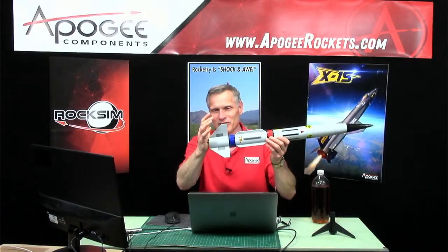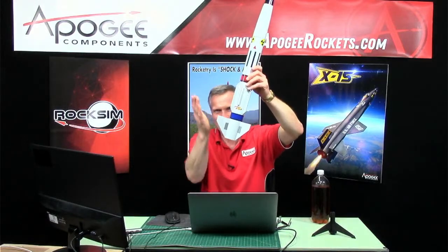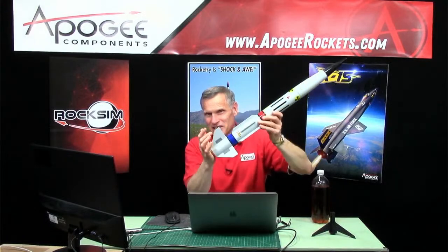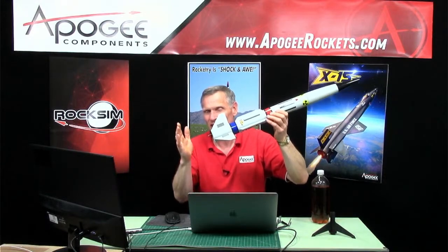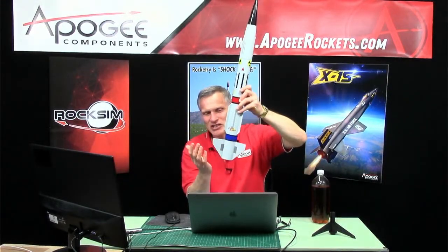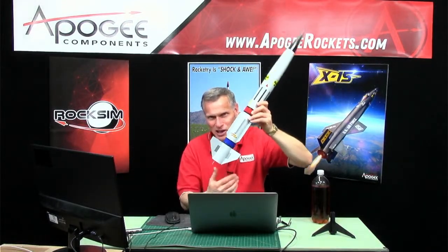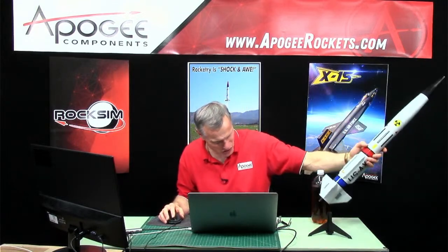You're probably going to crush something down here first, because usually it hits something. With these fins that angle forward, it's going to hit the tube first. And if you hang your engine out the back, then it hits the engine first. And that's a trick that I like to use as much as possible. When it hits the ground, land on the engine instead of the tube or the fins, and that will save your rocket from a lot of damage. Fins that hang off the back of the rocket, like the one that we have just shown on the screen, those would probably crunch the fins first.